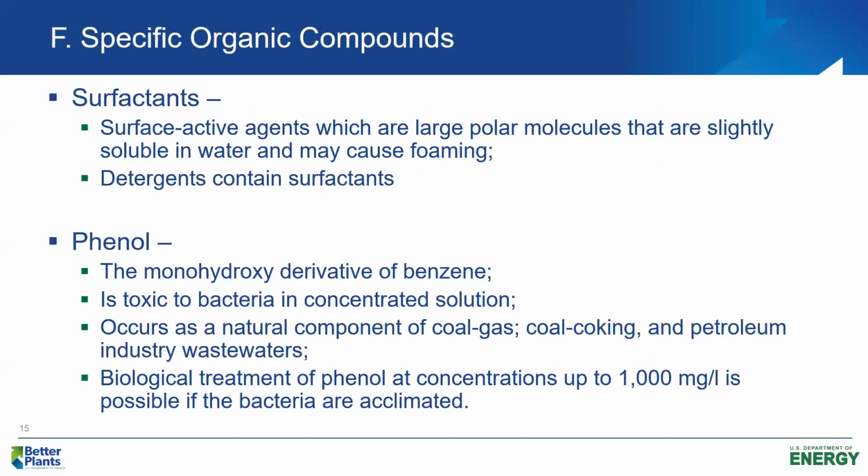Other constituents we're concerned about, surfactants. Many industries use surfactants in their process for a lot of different reasons. These are polar molecules, and usually one end of the molecule is soluble in water, the other end is soluble in oil and grease. And they have, again, widespread use in industry, but surfactants can cause us problems at the municipal wastewater treatment plant.